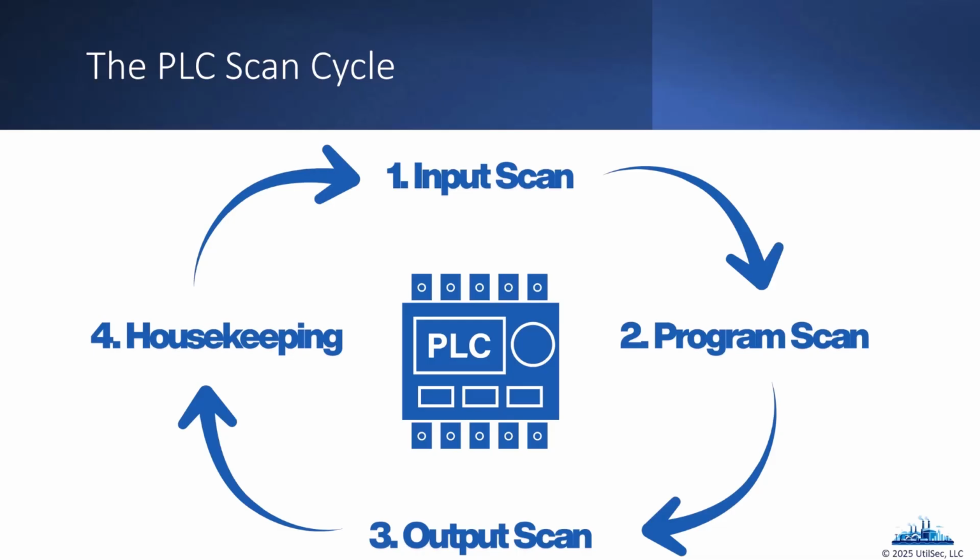So we just started to briefly talk about this earlier in the course, the PLC scan lifecycle. The first thing that the PLC does is it brings in data. It brings in the information from the sensors that we have in the environment to monitor, to understand what's going on in the environment. What's the pressure in this tank? Is this motor on? How much fluid is passing through this pipe at this one point in time? We have to bring in all of that data that we're using to monitor the environment.